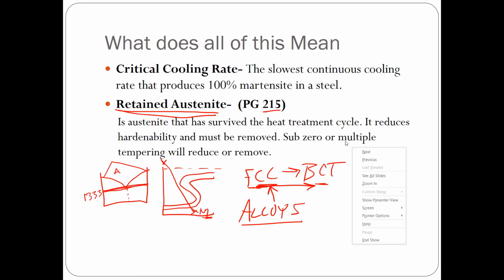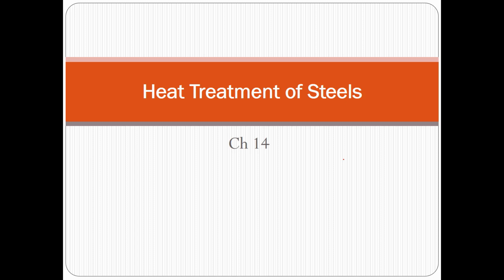Usually multiple temperings. So we'll double draw, triple draw, as the trade term might be. Drawing and tempering are the same thing. Specific heat treatments of steels, Chapter 14, which starts on 217 in your textbook.